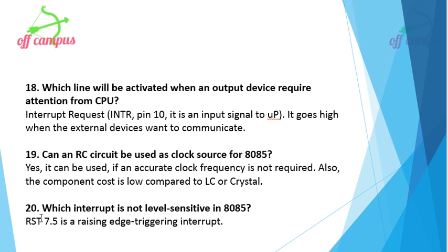Then, which interrupt is not level sensitive in 8085? RST 7.5 is a rising edge triggered interrupt. So it is not level sensitive; it is an edge triggered input.